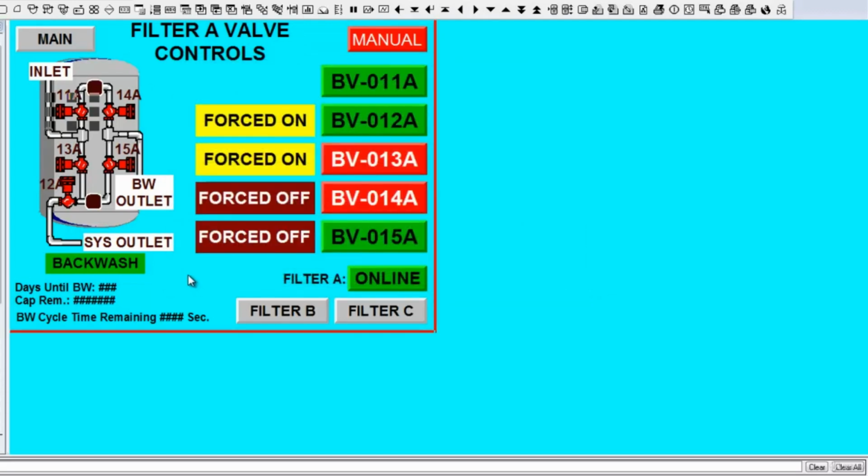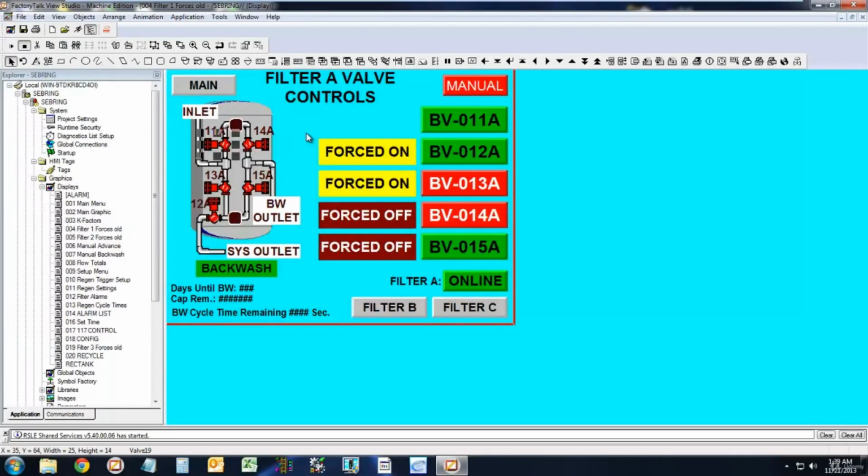And that is basically how all of the displays and all of the inputs on an HMI screen are set up. We're not going to go through every single instruction in this HMI development environment, but later on we will walk through setting a few of the more common controls up. Really, once you understand how to set up one or two of the controls in an HMI, the rest of them are pretty self-explanatory. They all have a simple behavior and they all associate with tags in our PLC.